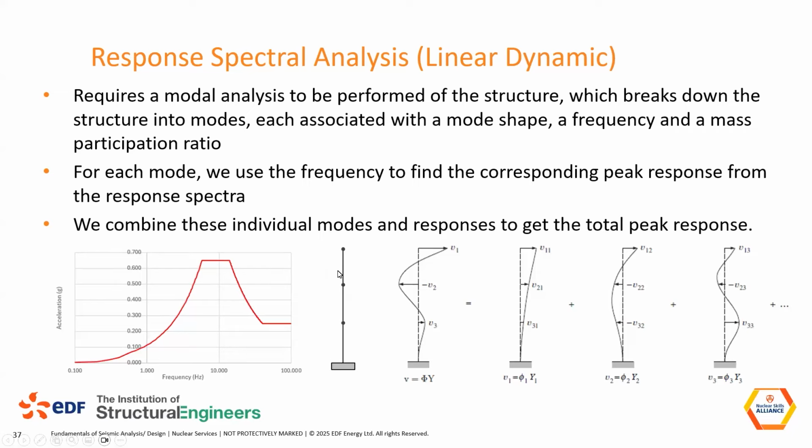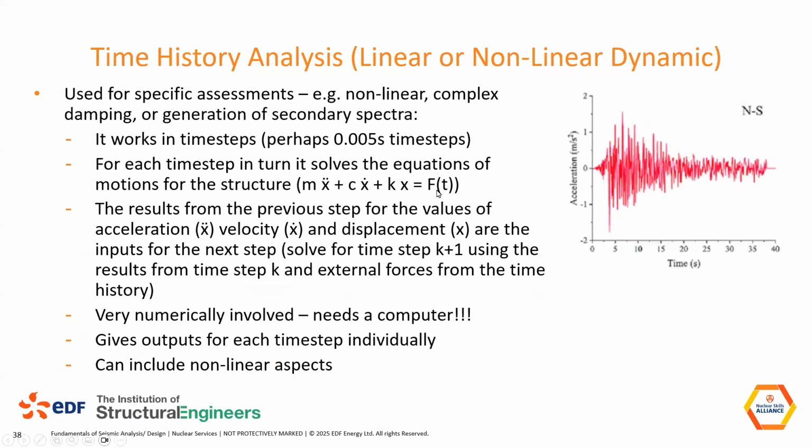But essentially, we have a simple structure which will have a response. That response can be made up of individual mode shapes, and we can resolve each of these individually and add them together. And that is essentially what we're doing. I think go and do research on this on your own if you want. It's just important that you understand response spectrum analysis. This is what we're doing. We are splitting the structure up into modes, resolving each mode individually, and then combining them at the end to get the total response. And it's only for linear elastic.